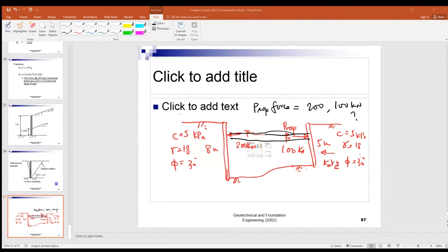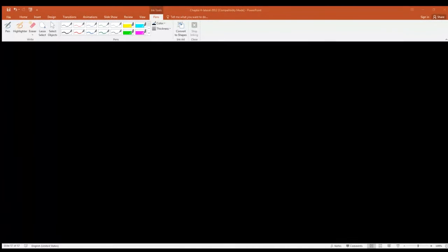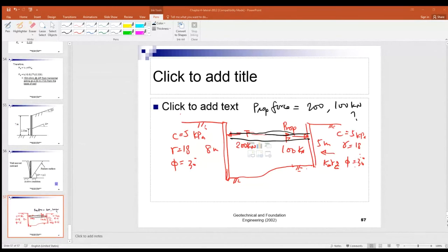Whenever any rain is pouring on the slope surface, the rainwater, right, will go down to the U channel, the surface channel, and discharge away, right? So any rainwater falling on the slope will be discharged as soon as possible, rather than leaving the heavy pour, right, dripping along the whole slope, right?